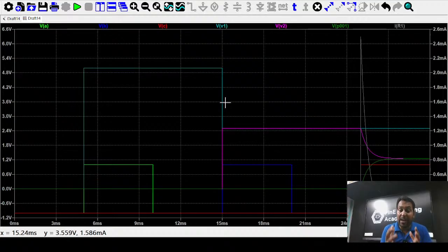So that's why it is rapidly changing with a very small duration of time. But whenever you have a resistance, it will not provide rapid changes. It has a tau. If you have a tau, it will affect your circuit and it will discharge exponentially. You can increase this time. If you make R from 1K to 10K, it will discharge very slowly. If you make R from 1K to 100 ohm, it will discharge very fast.